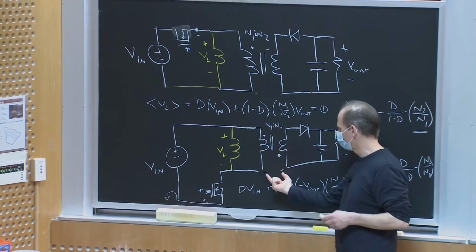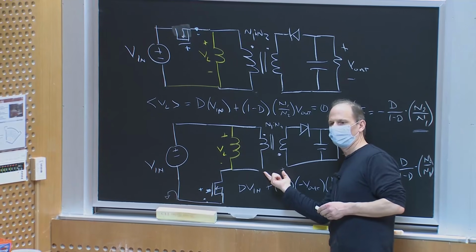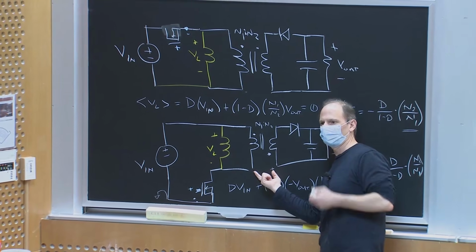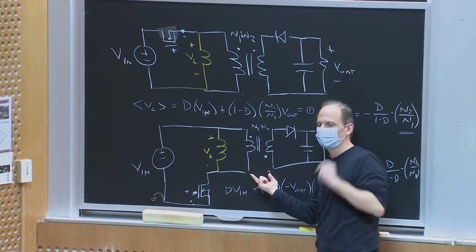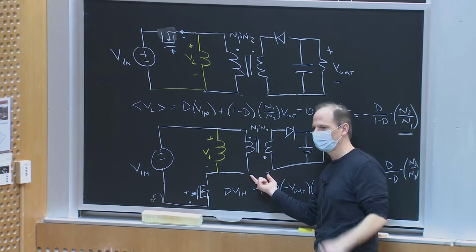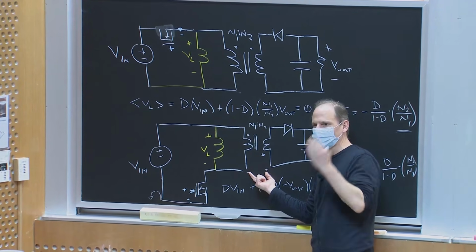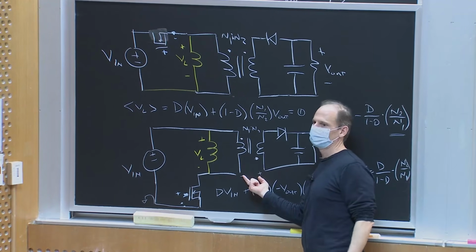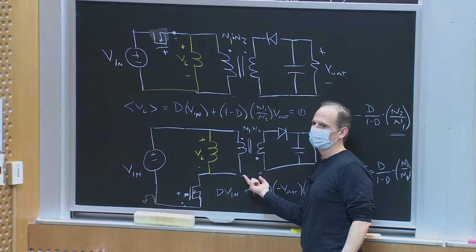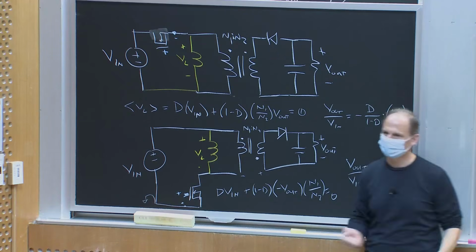this isn't perfect. The ability of the transformer to take voltage this way depends upon how much insulation you have between the primary and secondary, and that's what's regulated. So it's a few thousand volts typically for a laptop adapter. And like I said, even if you have a fault on one of those layers of insulation, the other one should be big enough to block a few thousand volts. Does that answer the question?